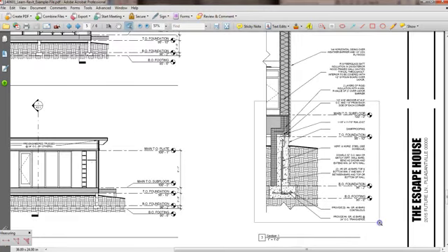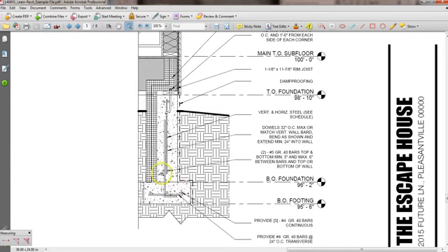And right now, we're just asking you to guess. Kind of a good rule of thumb, guys, is that you want all your rebar to be at least 3 inches away from the edge of the concrete, if possible. If this is only a 6 inch, it's not really going to work. I think we got an 8 inch right there.